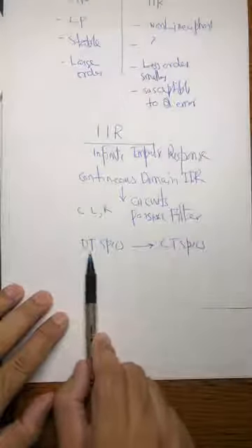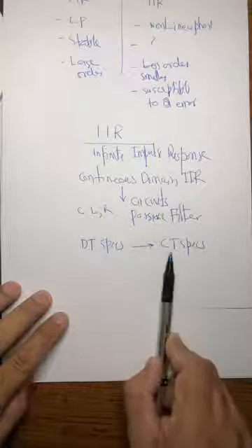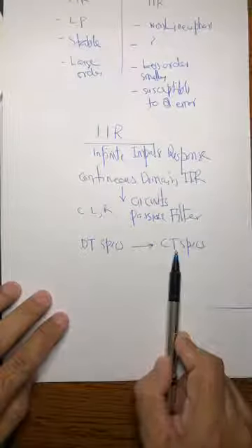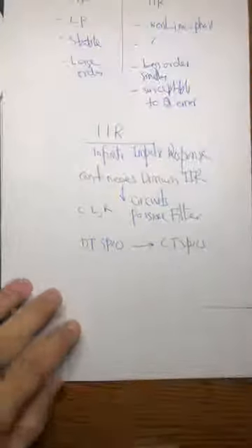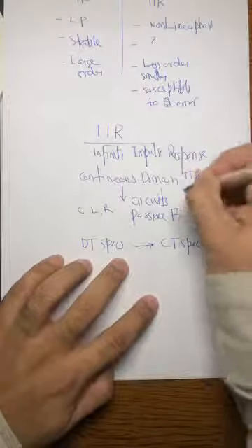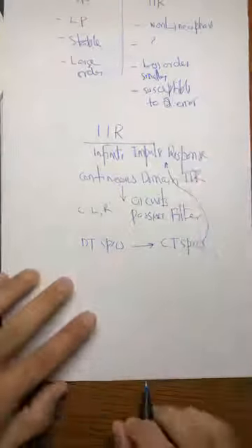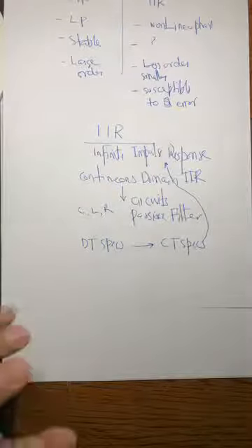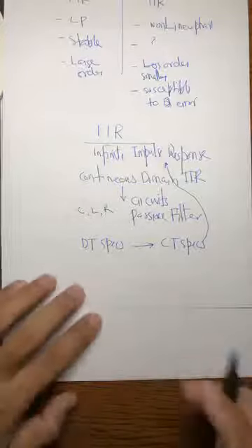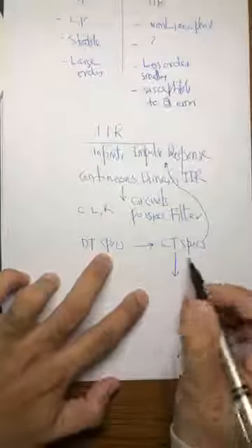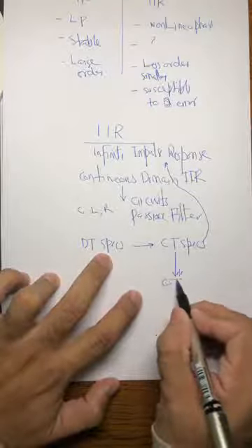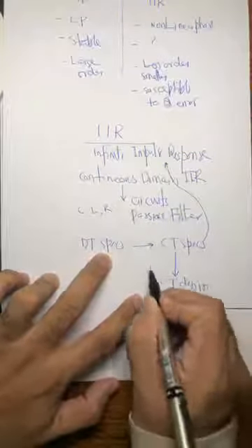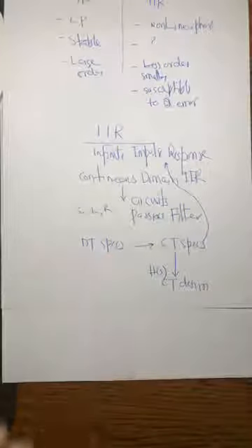If I have something in the discrete time domain, I can create even the specifications in continuous time. And now go back to history, go back to these people who have spent a lot of time designing continuous domain IIR filters. Use all the tricks and techniques which people have already developed and design. So this is a design problem. You design a continuous time filter, which usually is in the S domain. A transfer function is H(s).